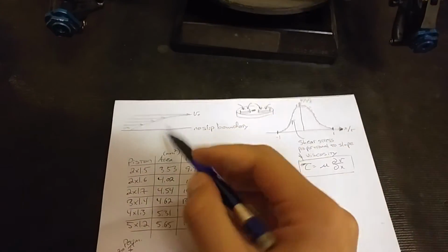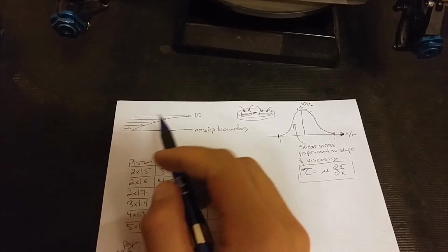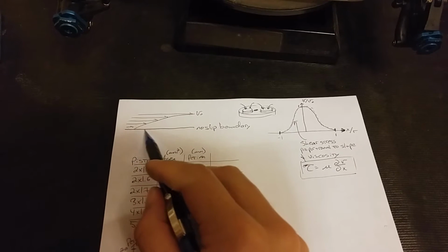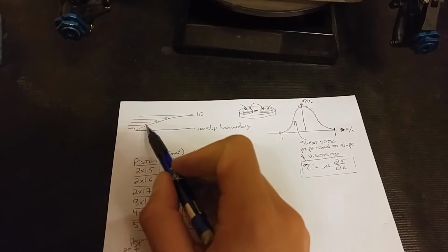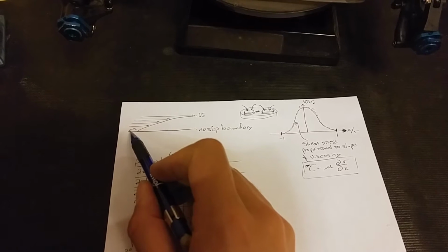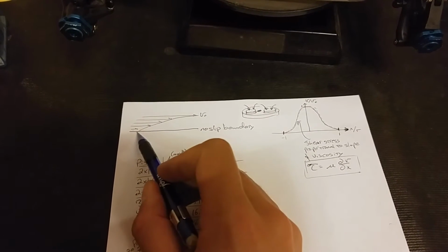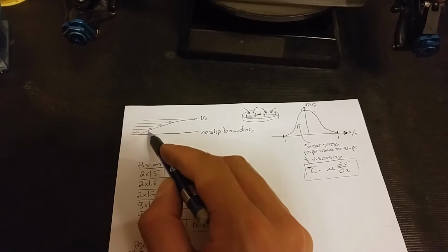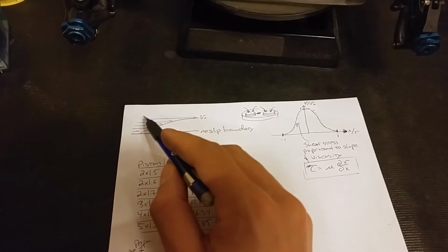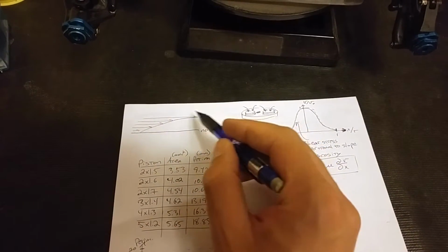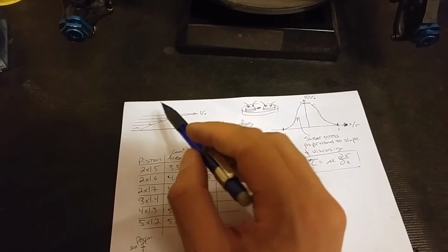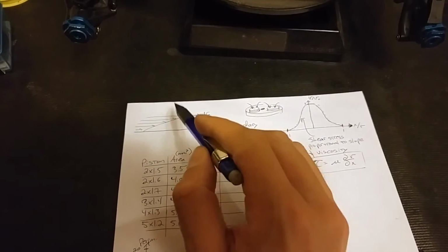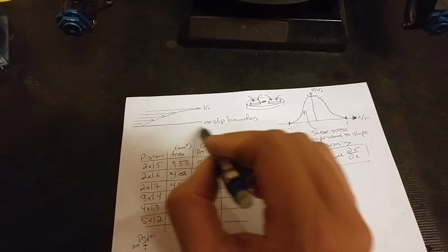So if you have a fluid, it could be water, it could be oil, it could be air, moving along a boundary. Let's suppose this line here represents a surface. We would generally expect the velocity of the fluid right at the surface to be 0. And then as we move incrementally further away from the surface, the velocity increases and approaches the free velocity or the main velocity of the gas or the fluid at an infinite distance away from the no-slip boundary.